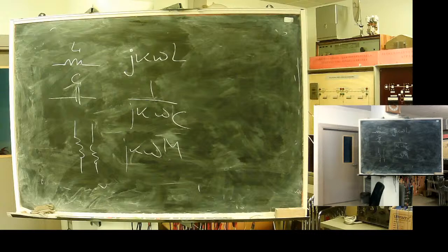Is this for the matrix or for something else? It's how we fill this matrix. We will have 50 matrices. Yes, exactly. But we don't need to store them in memory, since we calculate one regime in time, we will recalculate this matrix. For each AC component, we create its own resistance, or better, impedance matrix. The number of harmonics is 50, from 1 to 50. For each frequency, the matrix is recalculated and recreated.